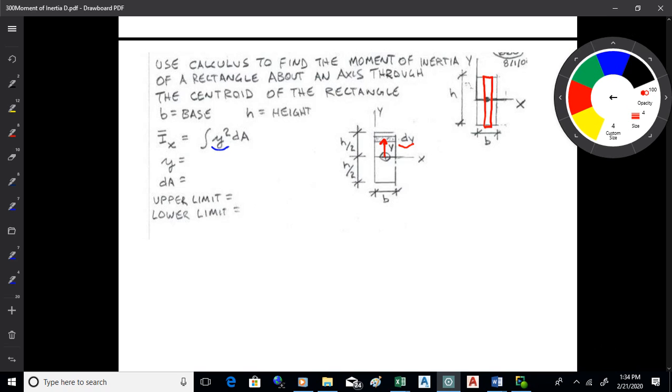So I would write a little program that says, okay, go out there and sample, tell me how far up you went to find that y. Now tell me what the area is. The area is whatever dy is, which is that thickness you would select, times the width, which is the base. So I would set an increment in a computer program to do this.